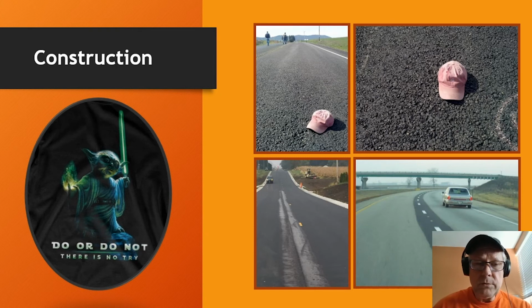So for some construction techniques, we want to avoid segregation. We want to avoid low density on our joints. We want to ensure smooth ride. It takes the right ingredients, the right production, and the right placement techniques. The photo on the left is closing down a joint by flooding it with a product that fills the surface voids and penetrates into the mixture so that it helps the roadway last longer.